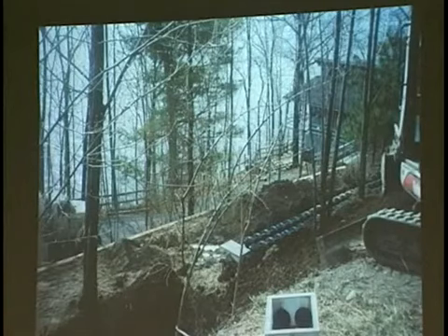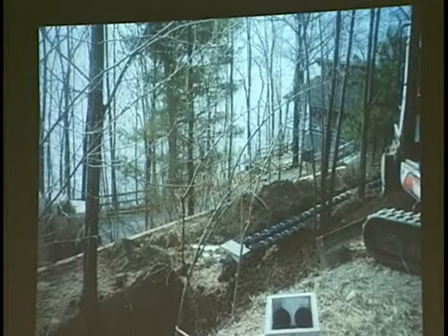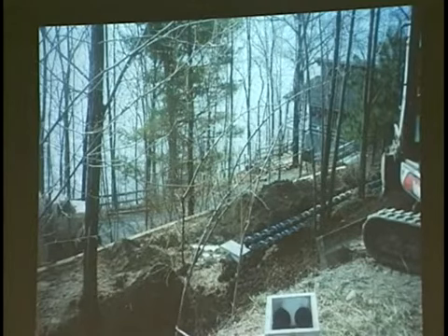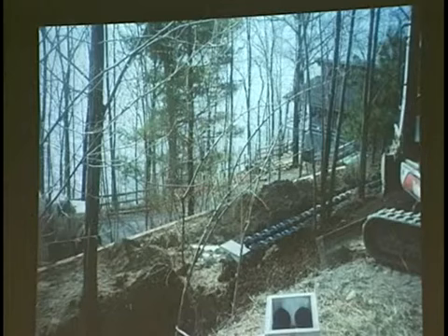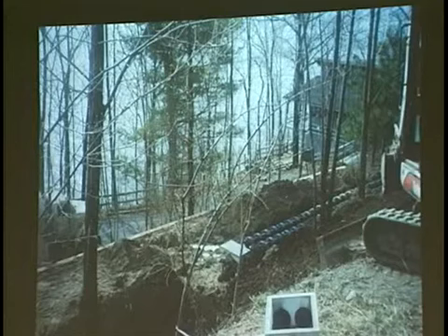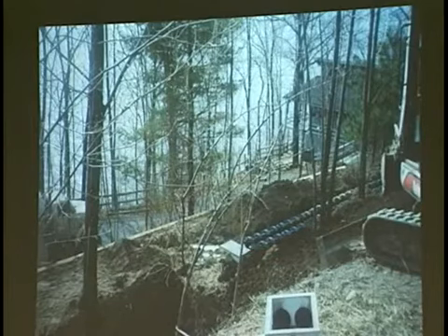What I'm going to show you now are some practical approaches of dealing with these severe sites. This place on Canandaigua Lake had a rusted out steel septic tank right here that went into a small seepage pit right next to the embankment that goes down to the lake. When that system failed and we got in here, we told them, again, the repair was going to meet the current health department standards as best as possible. We were going to get it back further from the lake. It's supposed to be a minimum 100 feet away from the lake. Also, we didn't have the proper soils there.